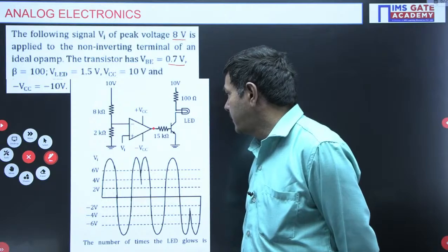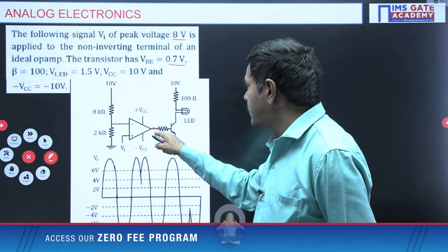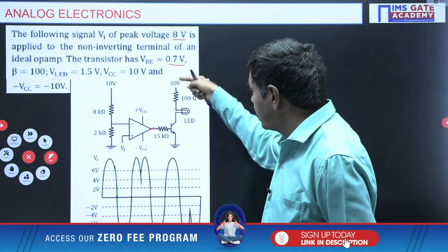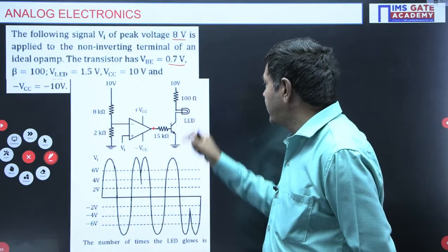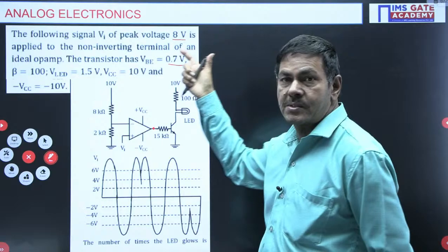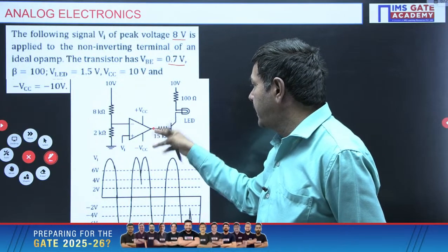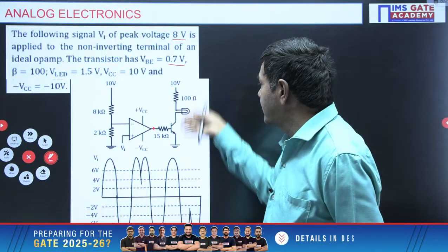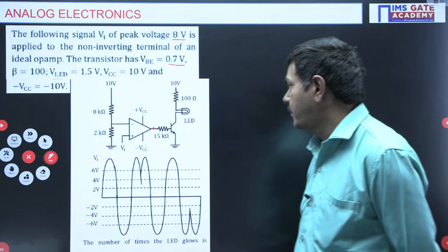Cut-off state only. Once the transistor is on because of the base voltage of VCC, collector current flows in the transistor. If the collector current passes through the transistor, the LED glows. If this base voltage becomes a negative voltage, the transistor is off, no doubt. If it is off, there is no IC and the LED will not glow. This point is very important.